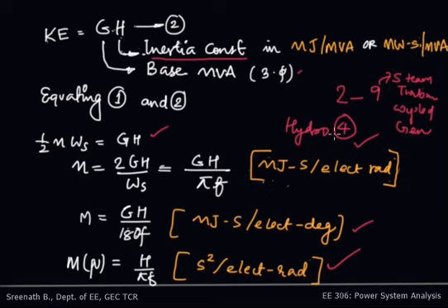So once you are trying to add more solar generators into the power system, whenever a solar fails, that failure of the solar has to be absorbed by some rotating mass. Some 100 kilowatt is failing, so that much energy has to be supplied suddenly from a rotating mass.